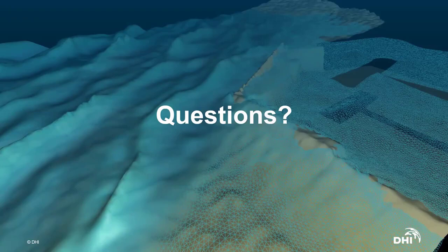Do you have any recommendation for mesh size for a typical wave penetration case? So the mesh for wave penetrations, I would suggest you to use at least 30 points per wavelength of the dominant wavelength that you are interested in. Can this software be employed for modeling tsunami? This has been done previously, and it has been actually quite successful. So yes, it can be done to model tsunamis.